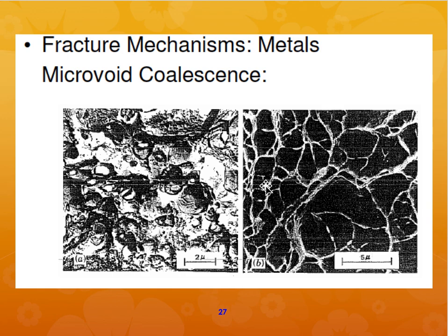The other type of failure could be in a polymer or even in the case of a metal. Suppose there are a lot of voids in the material. Suppose you are having a sample that is undergoing creep. And during the creep process, it has created a lot of small voids. And those voids all coalesce together and become a huge void.